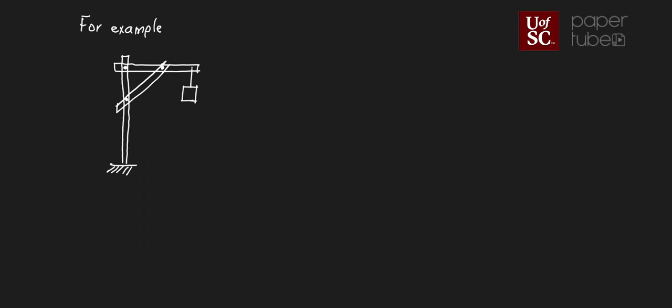So as a reminder, the two-force members are something like truss members, where they only have forces at the ends and they're connected by pins. So they do not have any bending moment, right? So in internal forces, they're only tension, compression. They're only normal forces.